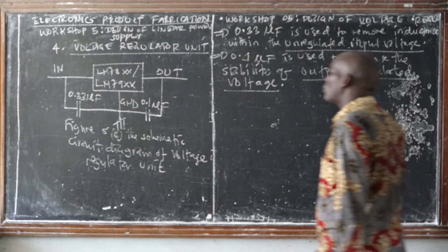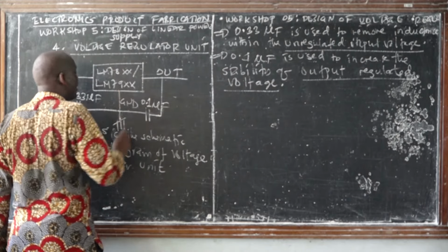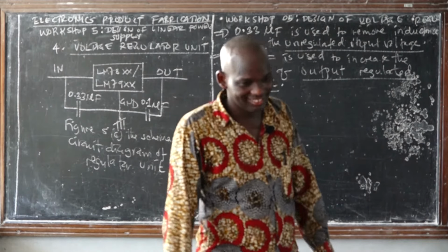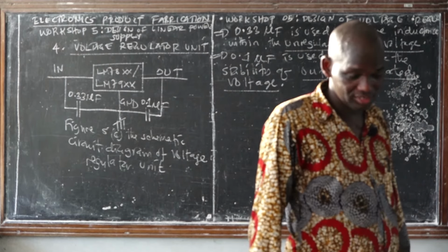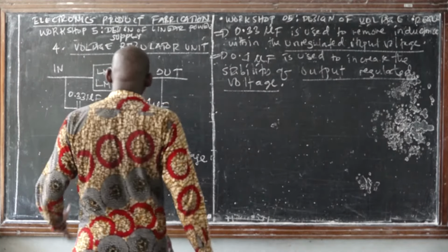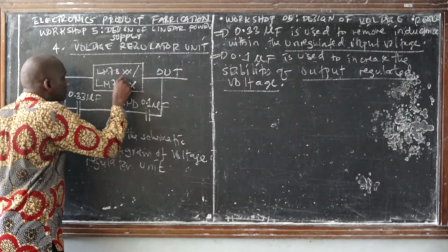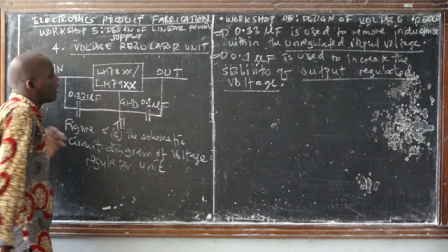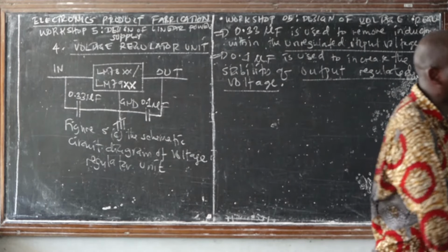So the answer to the second question, should I give it to you? I think I have to leave it. Go and find out how you calculate these and how you get these values. That's your homework. Will you go and find? Or you have looked and the information is not found? Okay, so let me help you answer the question. The values of these two capacitors, we who design different systems, we don't calculate them. These are the values that the manufacturer recommends to be connected externally.